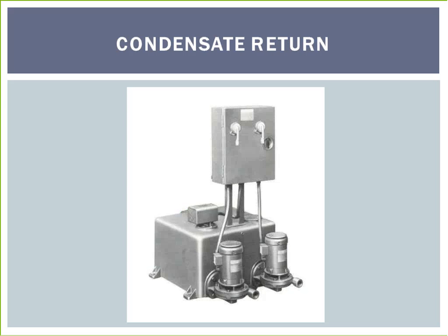Condensate from a steam boiler system is not mineral-free water. Strong consideration should be given to returning all usable condensate in order to minimize the use of cold makeup water, which must be heated prior to entering the boiler. An added benefit will be the decreased use of chemicals and improved boiler surfaces. This will reduce corrosion, which can lead to early failure, and/or the buildup of scale, which can hurt boiler efficiency.